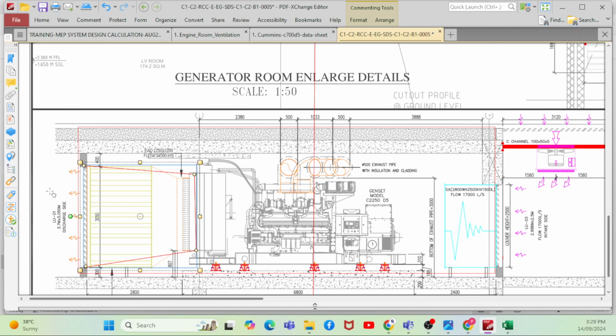Understood. Assume that instead of 95 pascal, it is 150 pascal because of my long duct routing. Then you will provide an extra fan for the discharge as well. Clear, that means in this case, Pranay, there would be scenarios where you might require both a supply fan and an exhaust fan because of the pressure drop requirements.